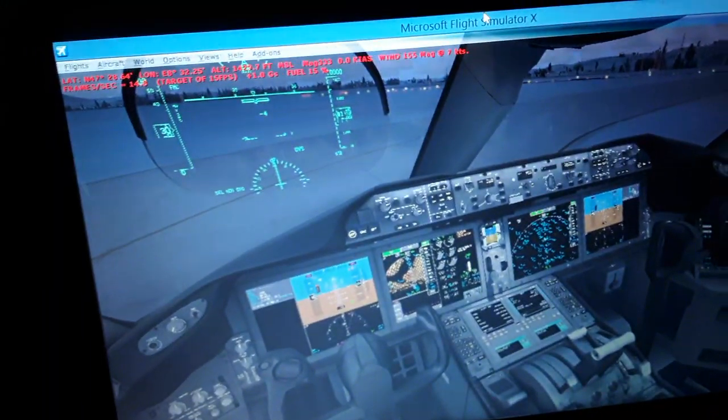Also using the stabilizer, the flaps position. I'm gonna use 15 degrees of flaps. Also we fly with burn fuel. The center of gravity is recalculated every second because it's shifted as we burn fuel in flight from takeoff, climb, cruise, descent, approach, and landing. Also the stabilizer trim is automatically set. You can set it manually.